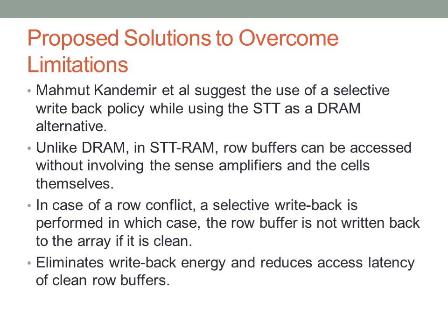Kandemir suggests the use of a selective write-back policy while using the STT as a DRAM alternative. In this case, a selective write-back policy is performed, in which case the row buffer is not written back to the array if it is clean. It is only written back if it is dirty. Kandemir found by simulations that almost 60% of his data was clean and thus eliminated a lot of write-back energy and reduced access latency of the clean row buffers.